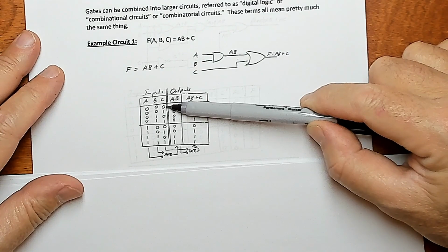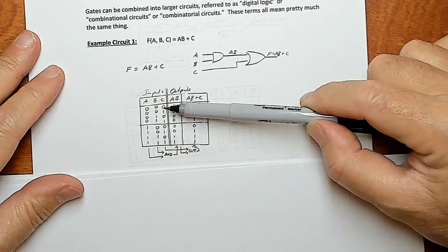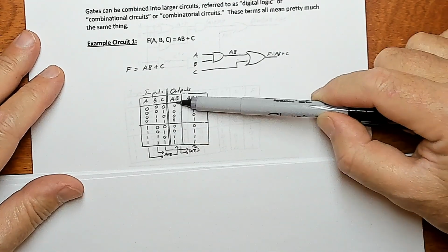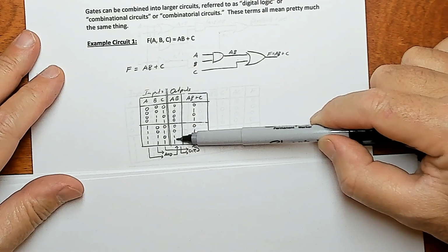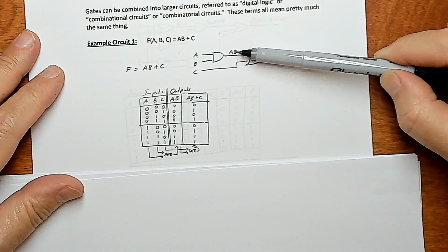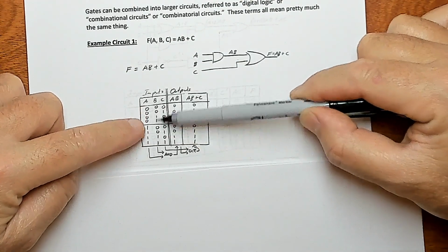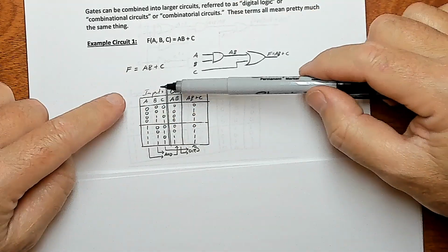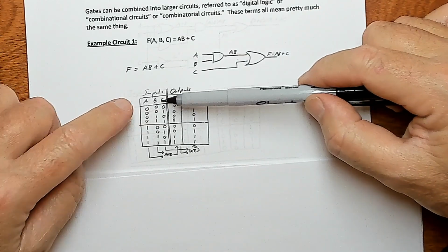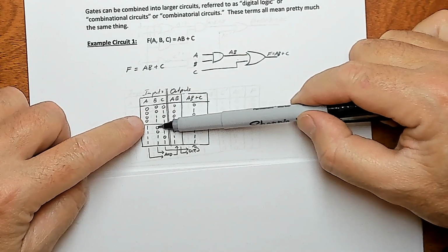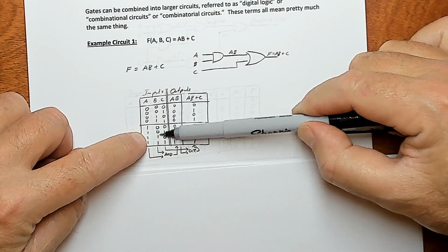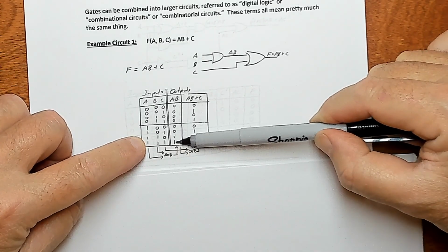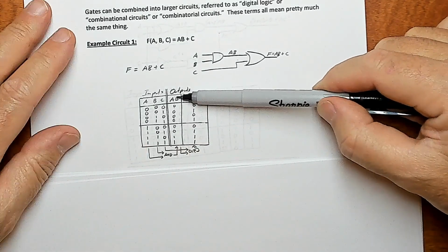In this case, on the input side we're just counting from 0 to 7 in binary, right? 0, 0, 0 to 1, 1, 1. And then we have the values of the intermediate columns that we've calculated here. For ab, we've just taken a and b and applied our definition of AND from the table on the previous page. So basically, we're looking for two ones. That happens here, 1, 1, so there'll be a 1 in the ab column. And then it happens again here, 1, 1, so there'll be a 1 in the ab column. The rest of the time it's 0.